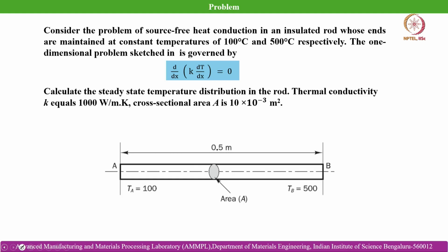Okay, so welcome back. In the last class, we discussed the finite volume formulation of a given governing equation, and here we will start with a representative problem and try to solve it by employing the finite volume technique. So, consider this problem of source-free heat conduction in an insulated rod whose ends are maintained at constant temperatures of 100 degrees centigrade at the left face and 500 degrees centigrade at the right face,